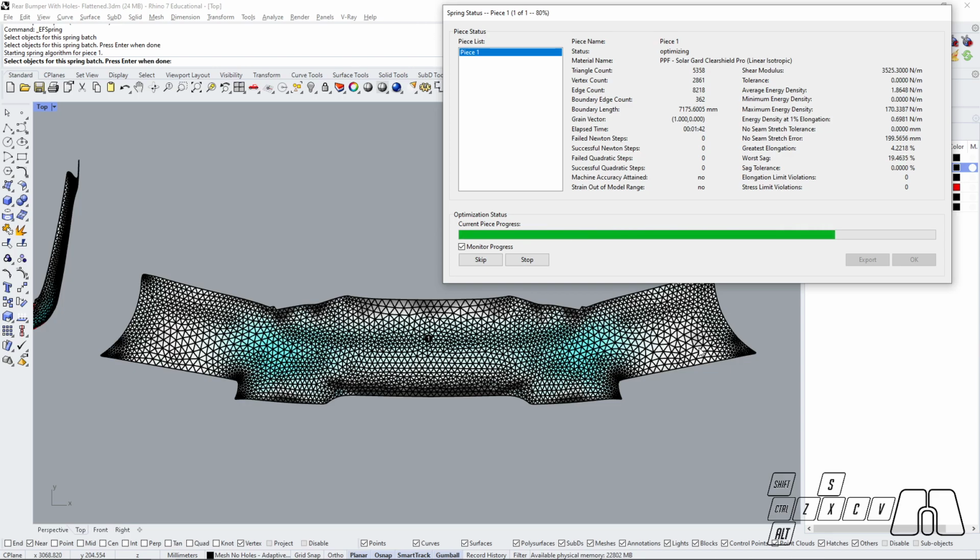So that means that whatever you see white, that means that you're not going to expect to have any strain there. Whenever you see cyan, that will mean that you're going to expect to have a 5% level of strain. Green will mean 10% level of strain, yellow 15%, and red 20% level of strain or more. If you happen to see any black shadowing like over here, that's going to be a representation of sag. That will basically mean that you're going to be having compression in your material instead of strain, right?